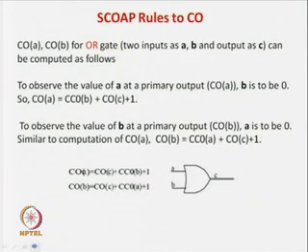For the OR gate, we always know that it is a dual of the AND gate. So, let us see that if you want to observe A, then obviously B has to be made 0. If B is 1, then C will become 1 and the whole purpose of test pattern is lost. So, combinational controllability of B to 0 you have to find out. And then combinational observability of C you have to take, because A is observed via C. So, that you have to add, plus 1 for the level shift.